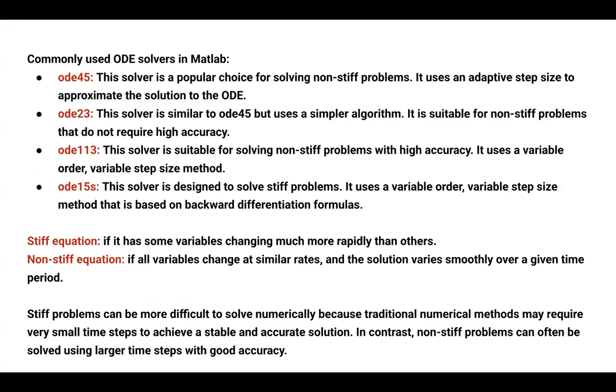And if you're not sure what solver to use, you can first start with ODE45 and see how the system behaves. Now, stiff problems can be more difficult to solve numerically because traditional numerical methods may require very small time steps to achieve a stable and accurate solution. In contrast, non-stiff problems can often be solved using large numerical time steps with good accuracy.